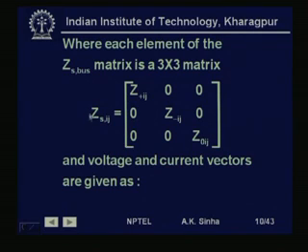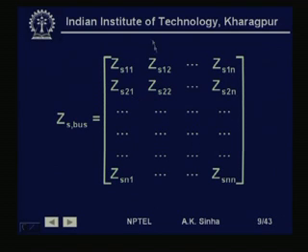So, this is what this ZS ij will look like. Any element ij of the ZS bus matrix will be a 3 by 3 matrix, where we have the positive sequence element ij from the positive sequence Z bus matrix as a diagonal element placed in position 1, the negative sequence in position 2, and the 0 sequence in position 3 of the diagonal. So, this will be a 3 by 3 diagonal matrix, where the positive, negative and 0 sequence impedance values are placed as the diagonals. So, we will have this n by n ZS bus, where each element of this ZS bus will be a 3 by 3 matrix. So, finally, we land with a 3n by 3n matrix.